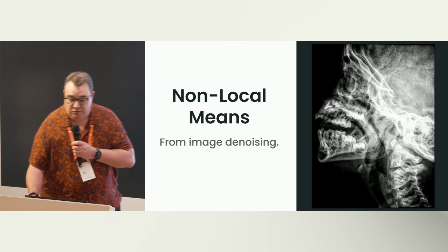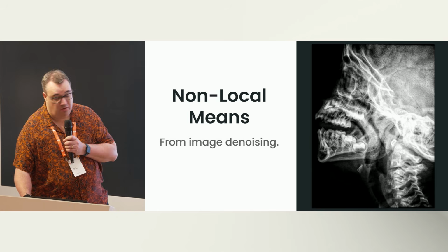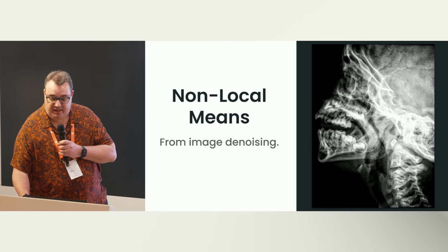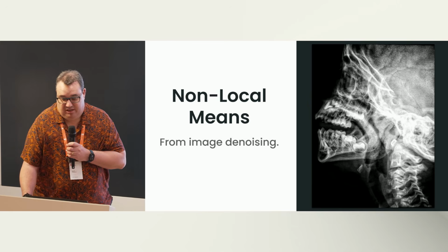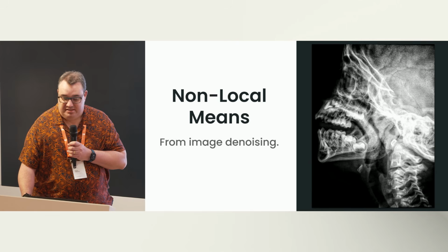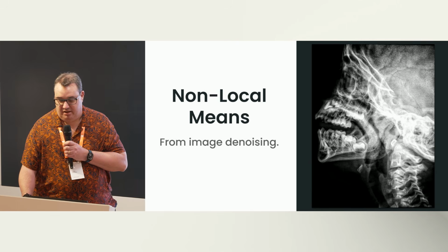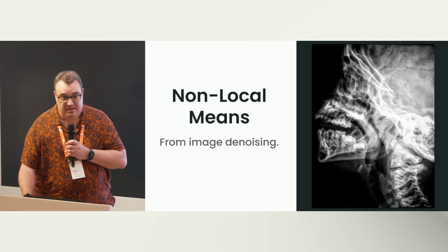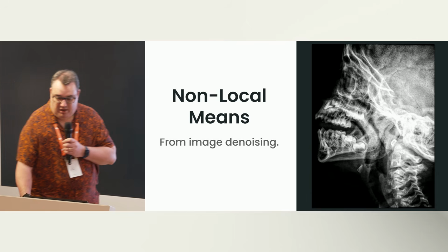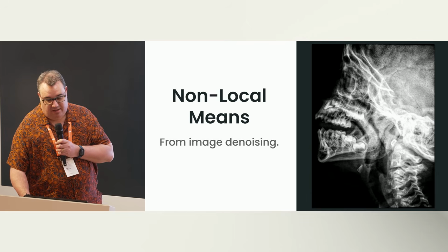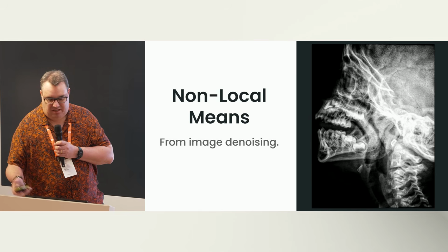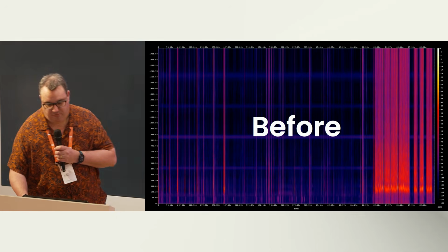I'm most pleased with the noise reduction. The first stage is non-local means denoising, a technique now common in medical imaging for cleaning up MRI scans. It treats the audio spectrogram as a 2D signal, finds the patterns across it, and treats everything else as noise. The second stage is a Dolby SR-inspired compander that squeezes the hiss that the denoiser may have missed. Here's a before and after.